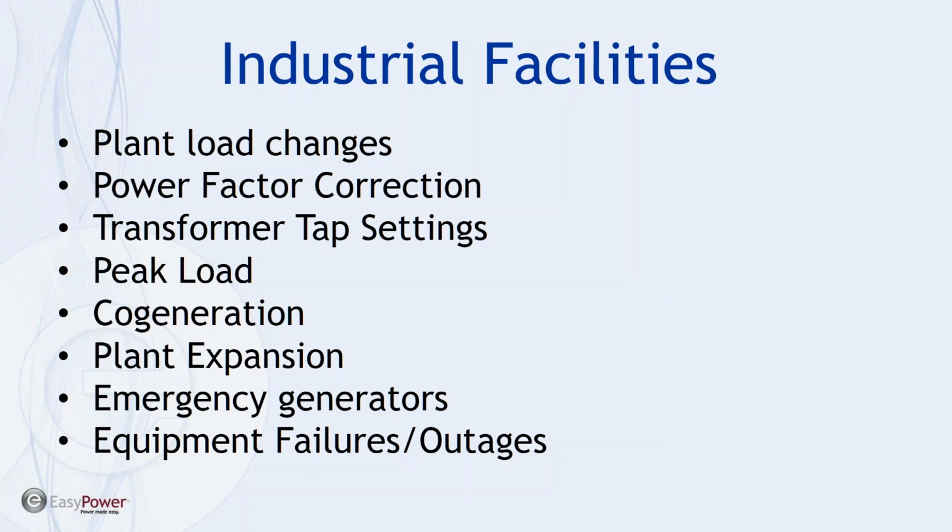Again, optimizing transformer taps, being able to track and anticipate peak load conditions. Seriously, if we have a cogeneration situation or even a microgrid situation, arc flash is not going to tell us too much other than that worst case scenario, whereas having an ongoing trend analysis or status of power flow at different cogen plant operations could be extremely valuable.